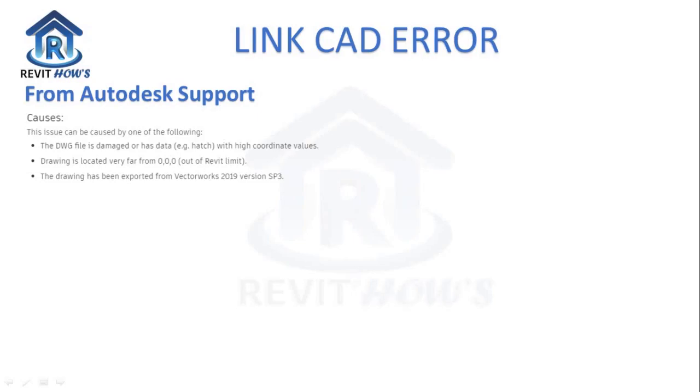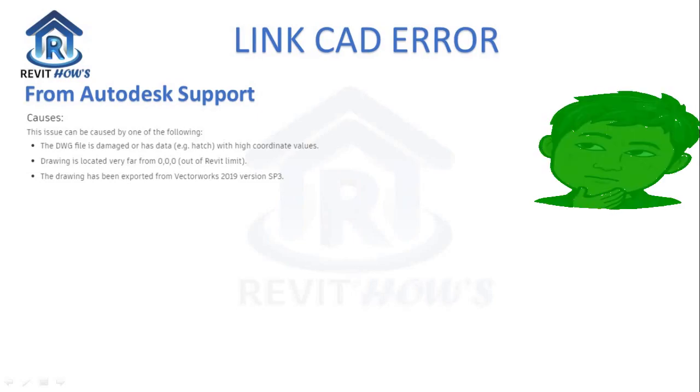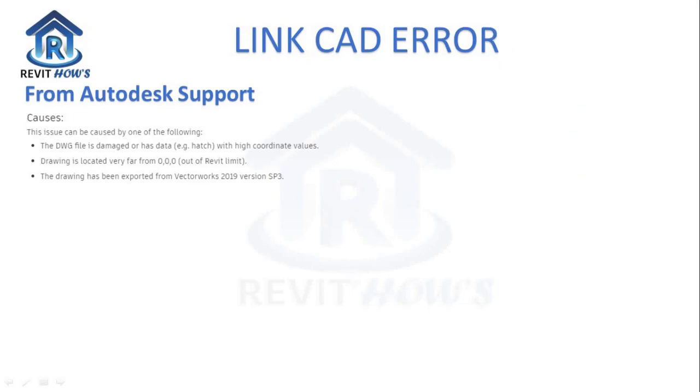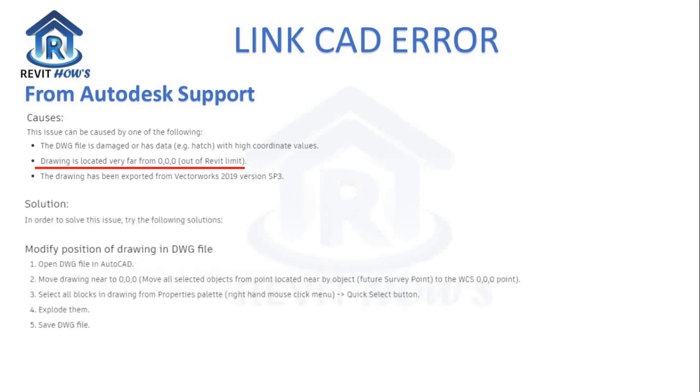What Autodesk Support tells you when you Google it is that these are the causes of this kind of error: either the drawing file is damaged, or the drawing is located very far from 0,0, or the drawing has been exported from Vectorworks 2019 version SP3. Most likely it's the second one. So as per the Autodesk solution, you have to move the drawing near to the 0,0.